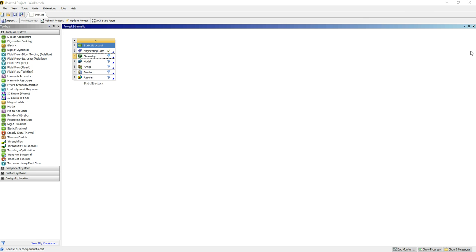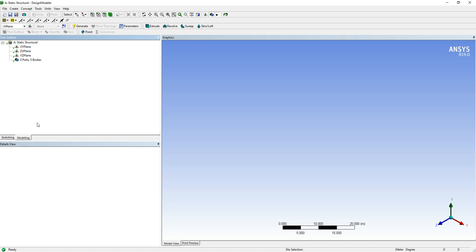And just realize it's opened up outside of your viewing window. So when it opens, this is what you will get. If you get something that comes up and asks you for units, make sure you click millimeters. And right, so let's do a bar. Let's go 60 millimeters of diameter, so it's quite a hefty bar. And then we'll put it out at 550, 600 millimeters in length.